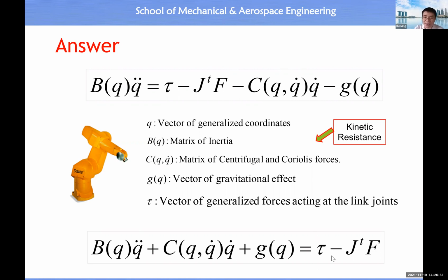Okay. So that means the torque comes from each joint. We put them together into a vector, minus out the energy spent for interaction with the environment. And the remaining energy will be used to overcome gravitational effect and Coriolis force. Then the remaining energy will contribute to angular acceleration by this moment of inertia. All right. So this is the physical meaning. So this is an equation, the dynamic equation at the link joint. All right, done already. So now we know this.